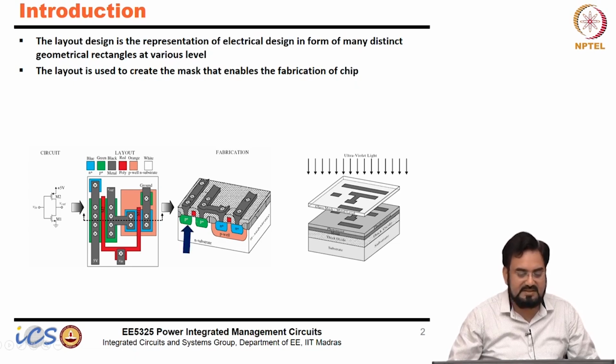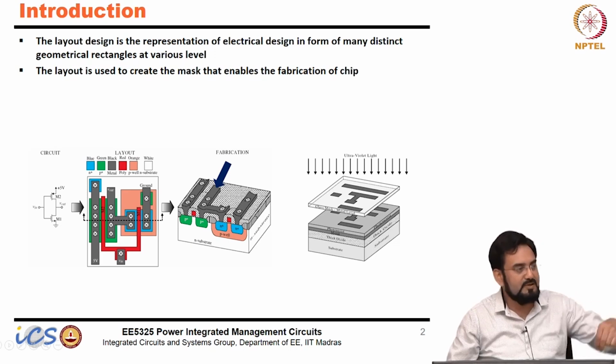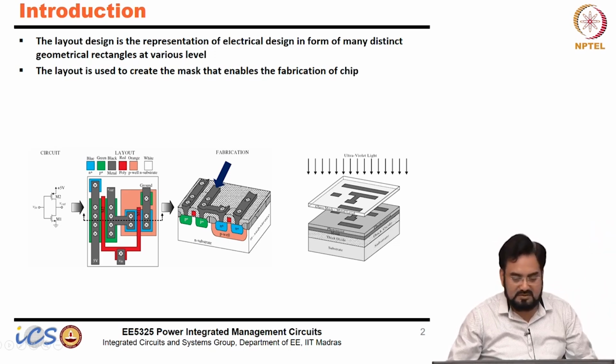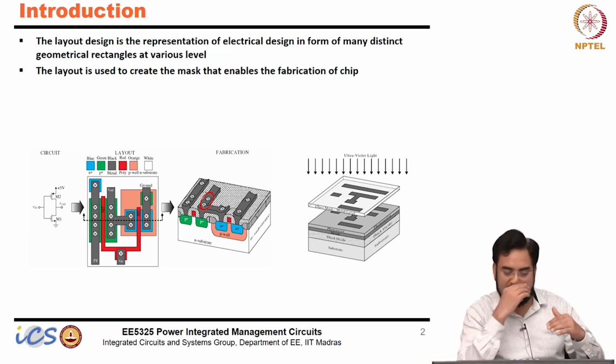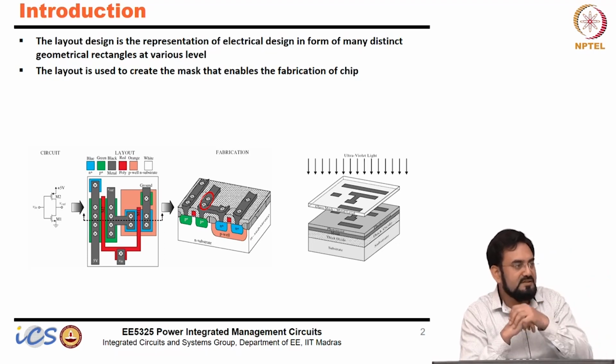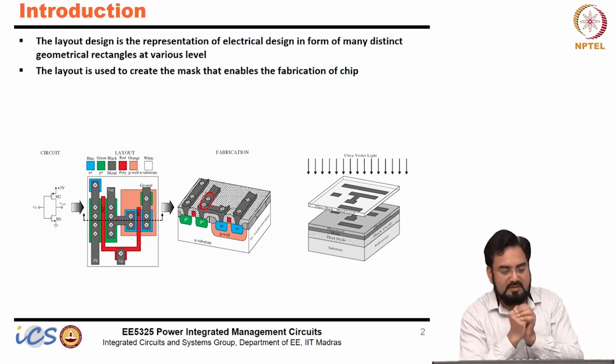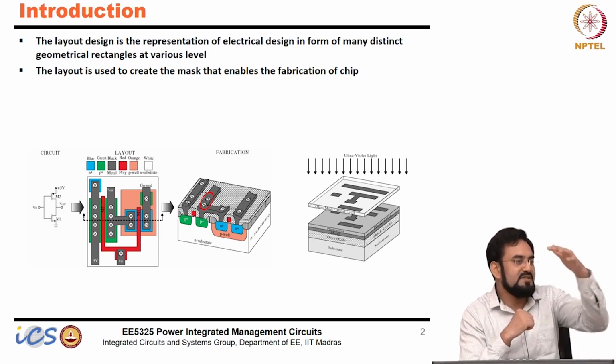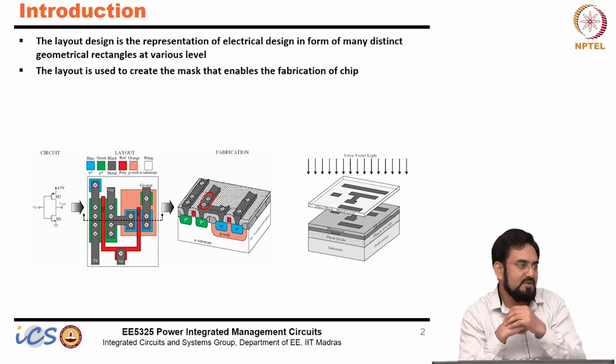Then you have the PMOS device here. You grow two P plus regions, one becomes source, the other becomes drain, then again the gate, and everything has to be connected to metal with a contact. So this diffusion you connect with the metal through contacts. Contacts are nothing but again the metal. Since you are connecting one layer with the other layer, you can think of it like connecting diffusion with the metal, so you need to create some contact.